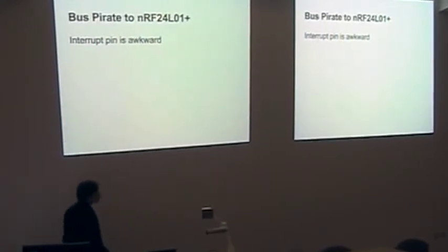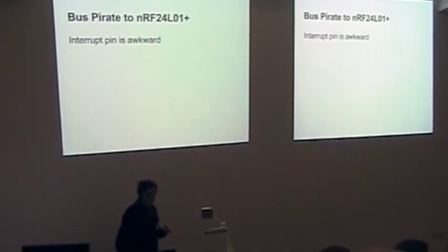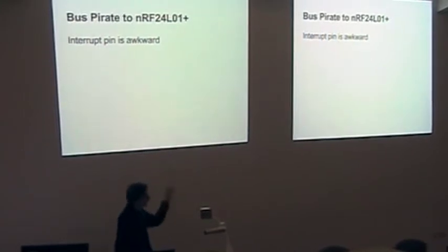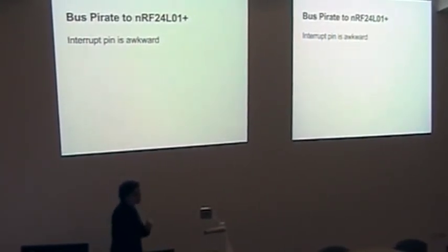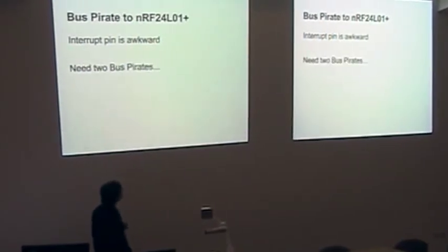Yes, but the one slight annoyance is that the thing does have an interrupt pin that tells you it's ready now, but you have to poll it. The Bus Pirate itself doesn't have any way to do interrupts.